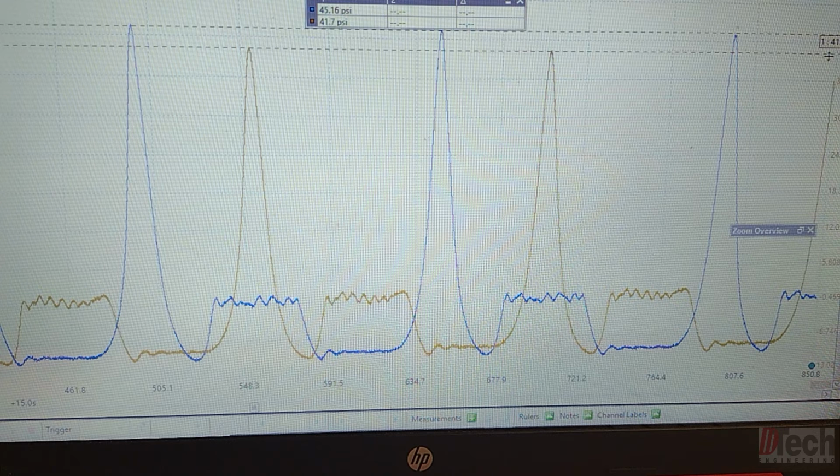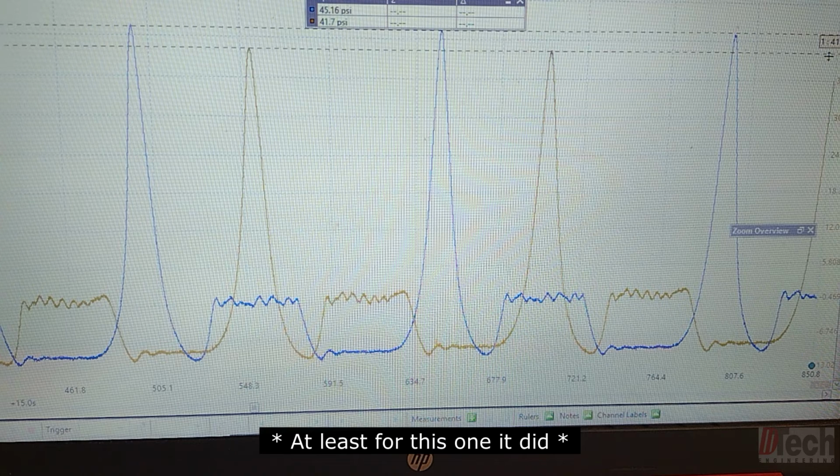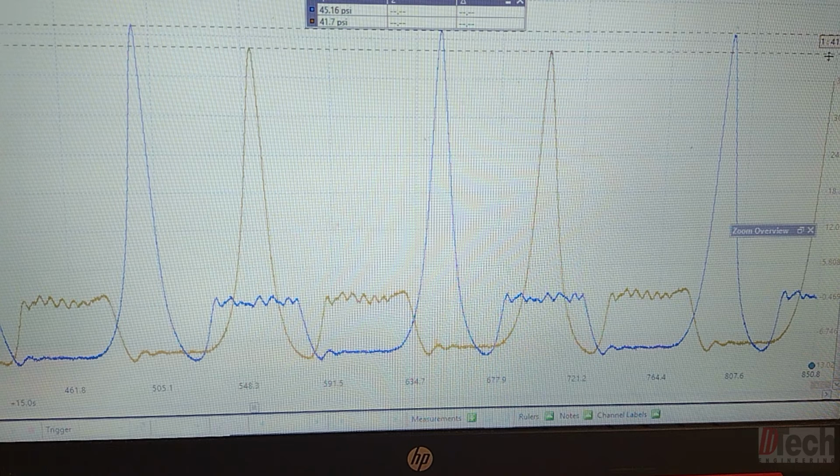And what I ended up finding is that cranking in-cylinder waveforms give and tell more of a story for sure, and give you all the detail of what's truly going on compared to running in-cylinder. This only tells us that there is a difference in peak compression pressure when idling.